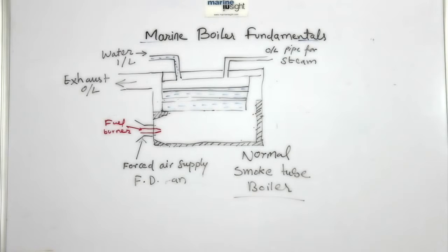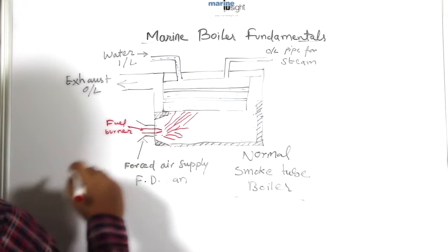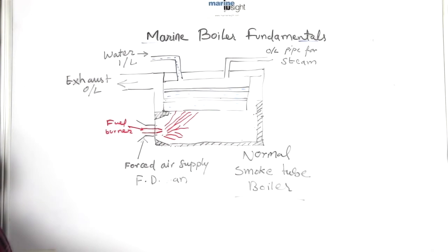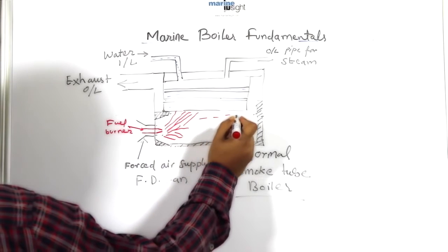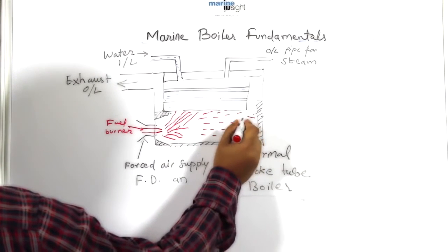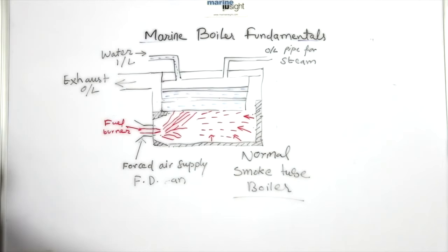Now let's understand how radiation, convection and conduction processes are involved in heating of water inside the boiler. The flame from the burner directly heats the water drum. The water molecules at the bottom part heat up and their density is reduced. This leads to heated molecules rising up and displacing the cold molecules to the bottom part. In this way, the water is heated due to the convection effect. The hot electromagnetic waves from the burner travel forward in the furnace and heat up the drum by the radiation process. The refractory helps in directing these electromagnetic waves and also contains the heat inside the furnace to avoid heat loss.